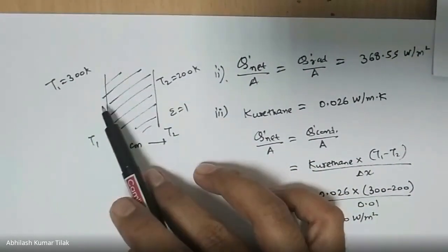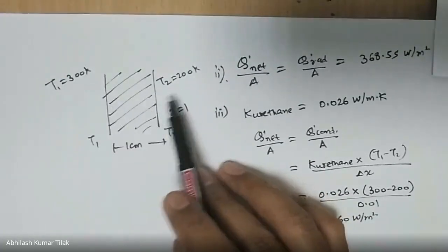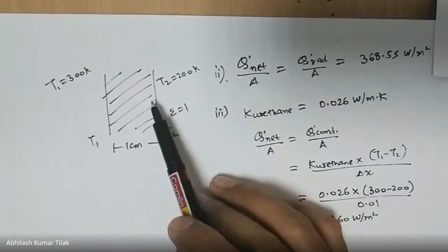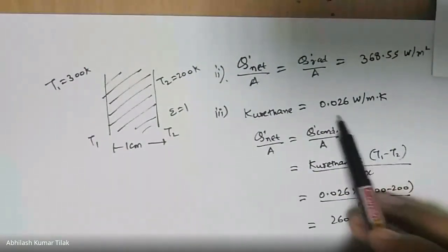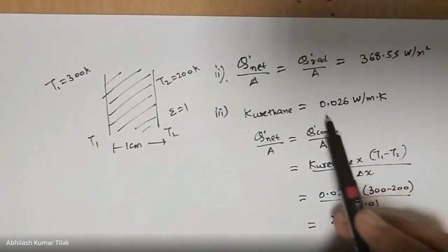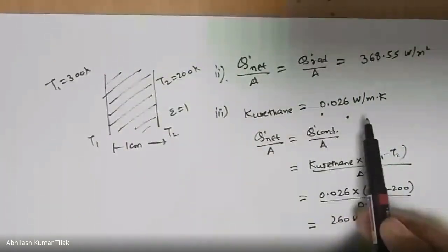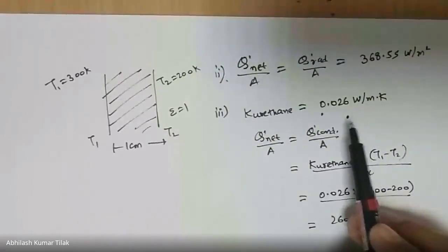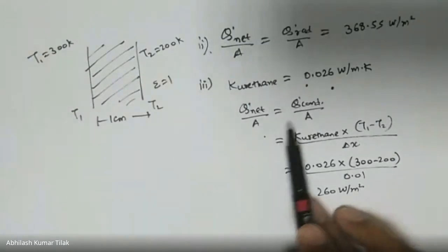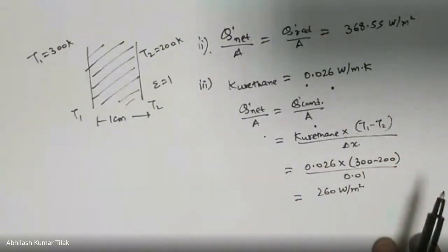The radiation heat transfer won't have a very smooth path from one plate to the other. It might be through the pores or the voids of the insulation. That would be very small, and it is itself accounted in the value of the thermal conductivity. Whatever the radiation is, it might be minimal, but it is accounted here in this value. So I can have Q net by area equal to only Q conduction by area. I hope this is now clear.